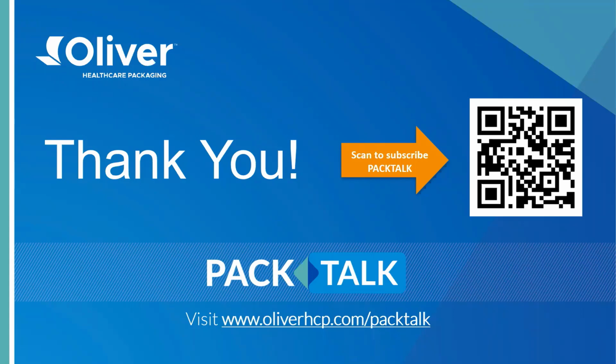From a limitation standpoint, well, I guess I could answer it like the limitations in temperature are going to be driven by the materials that are being dried. So I'm going to keep using DuPont Tyvek as an example. If we're running coated Tyvek through our drying operation, obviously, Tyvek is high density polyethylene, so you have to stay away from the melt points of Tyvek. You're going to have to keep your temperatures in check, or otherwise the Tyvek is going to start to pucker or shrink up. So the limitations are typically going to be driven by the materials that are coated, I think is a probably quick answer.